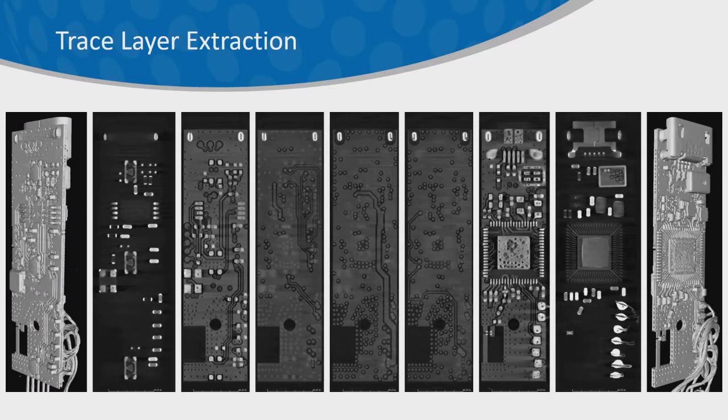So these images could be thresholded and put out into other software packages. The other thing you'll notice too is we can see even the quality of how parts are bonded to it. So we can do some level of component identification, looking at how components are attached, where some of the pin locations go. We can also look at things like defects in solder if that's significant. So this kind of gives you a sense of a lot of what can be captured with CT and exported with a CT file.